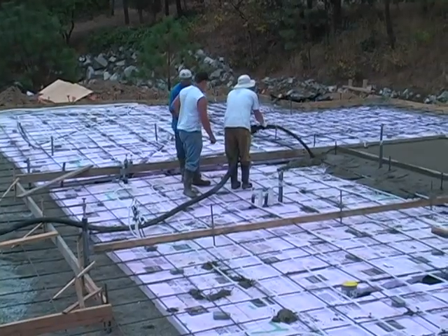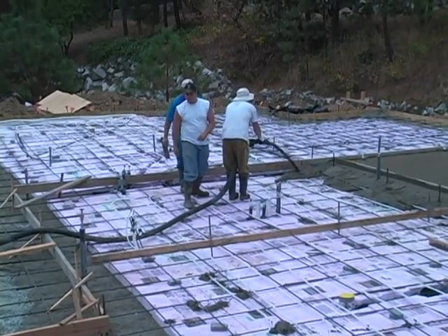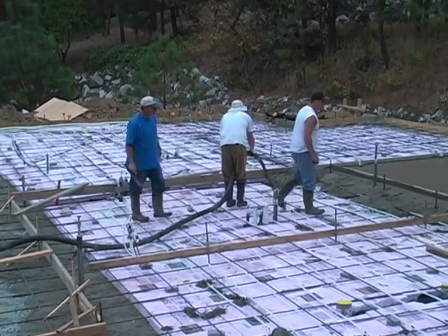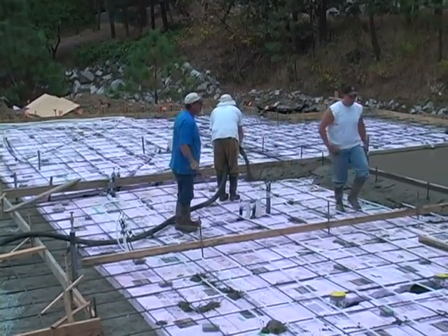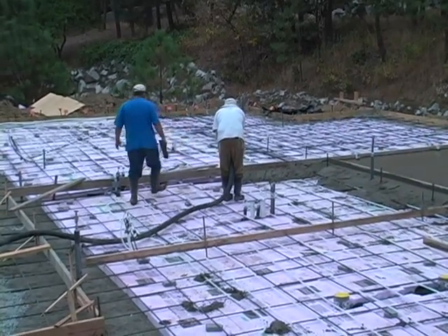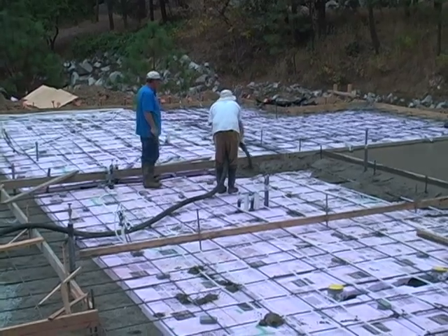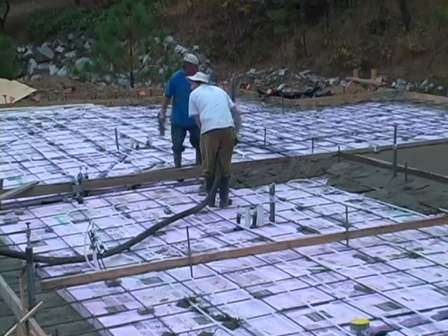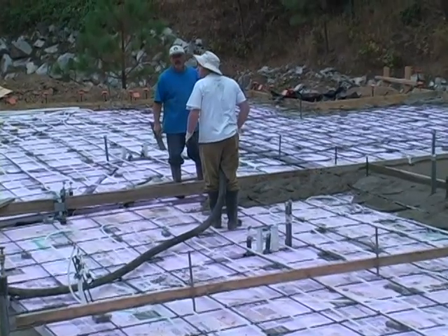So now again, we're using the concrete pumper to place the concrete in position. You can see we've got, running from left to right here, removable screed boards on our screed posts, and then to the far left of the picture we have a shutoff, which means that we've got a board that will stay permanently for the duration of this pour, so that we don't run into the next area of our pour.